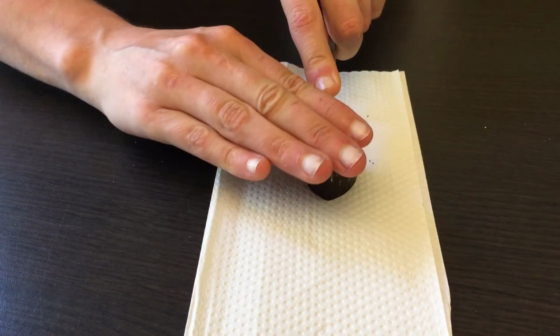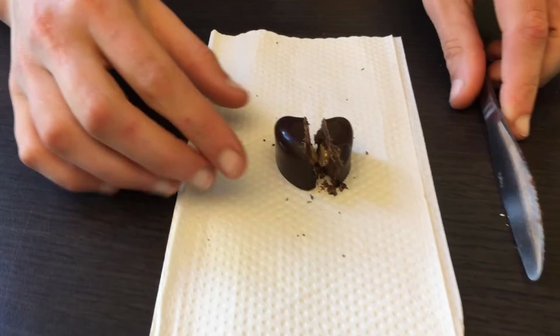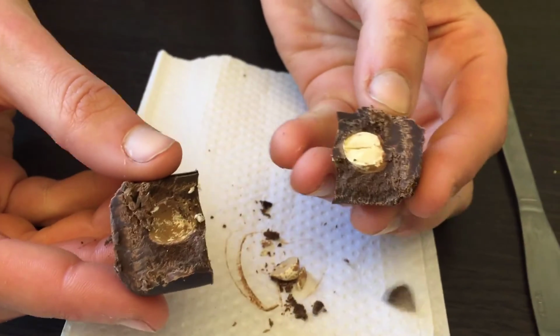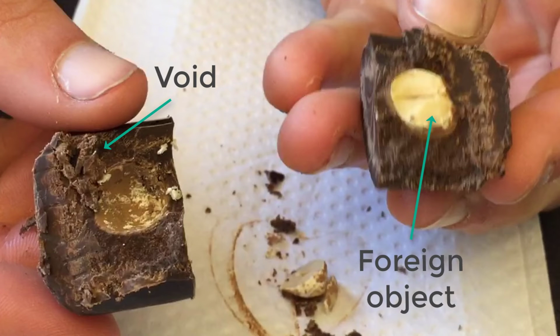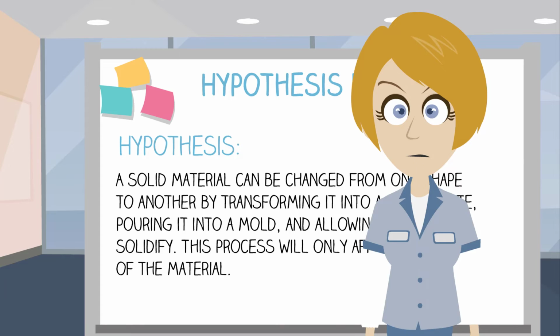However, in our second comparison, we can see some interesting features in the molded chocolate. In the molded chocolate, there appears to be an air bubble or void in the material. Additionally, there also appears to be a small piece of foreign material in the molded chocolate. It appears something has contaminated our chocolate, perhaps due to the mold not being entirely clean when the chocolate was poured into it. So now what can we conclude from our experiment?